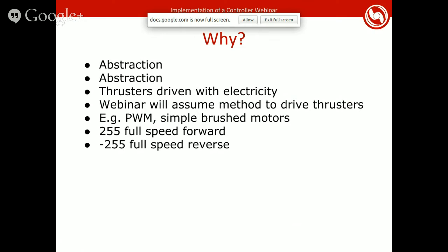And this is nice, but sometimes when you want to build up an autonomous mission, you want to do higher level things such as, complete this task and ram this buoy. That's hard to do just by working at such a low level. So the controller is meant to provide a layer of abstraction that allows you to set your motor values indirectly through higher level commands such as go forward or go west 3 meters, and then change your heading to be 60 degrees, and so on and so forth.